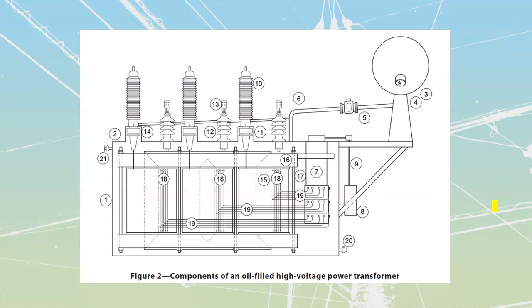There's an equation, we talk about this often, they call it the Arrhenius, I don't know how you pronounce that, Arrhenius equation, but it basically says that your life expectancy for electrical insulation is going to cut in half for every 10 degrees increase in operating temperature. Generally speaking, as a rule of thumb. Over top of 30 degrees is usually where we start that, so if you go 30 to 40, you're going to get about 50% less life. 40 to 50, you're going to get 50% less of that 50% less. So you're going to be down to about 25% life, etc. So the more heat that we allow to be maintained on an object, the greater the chance of failure. Because of this, we're going to try to cool our transformers as effectively as possible.